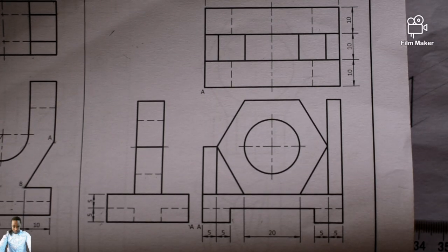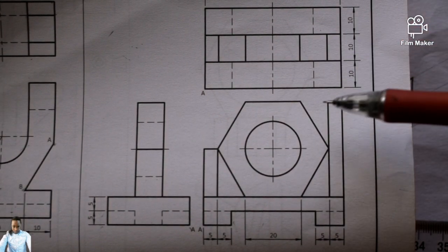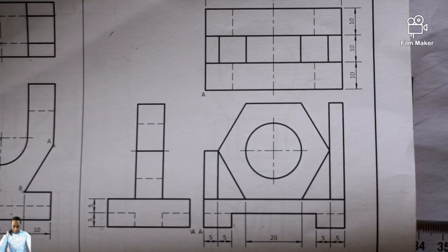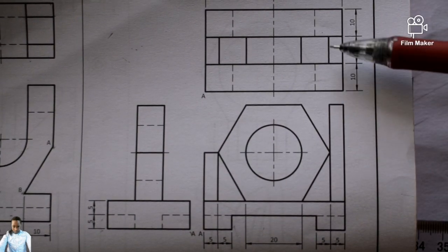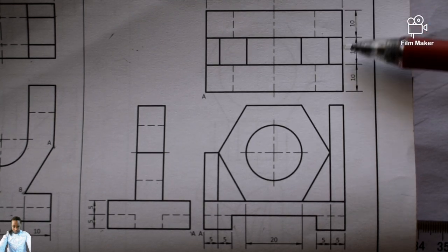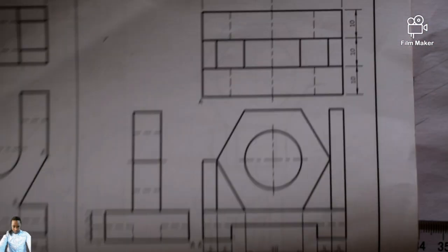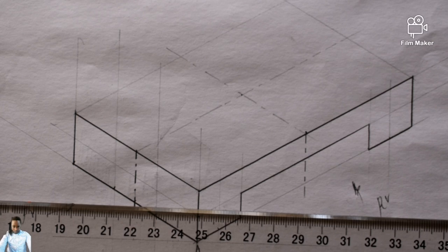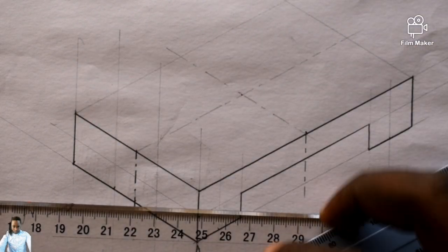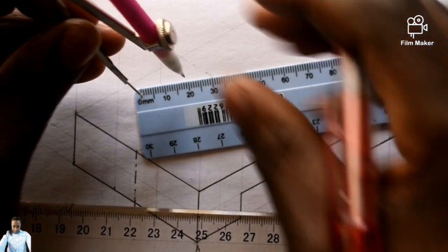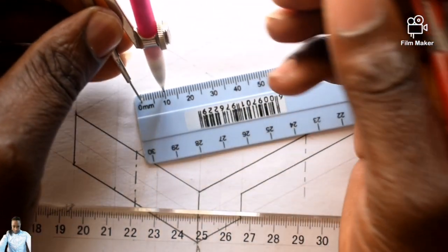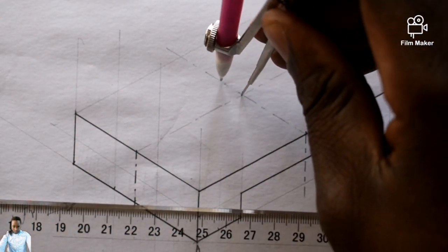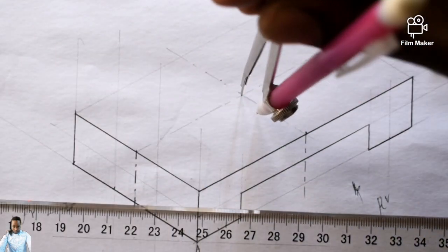And the thickness of it is how much? Is 10 millimeter. The thickness of this hexagon of ours is 10 millimeter, which is from here till here. We are being told a dimension for us there, up there by your top view. So it's 10 millimeter. So I am going to say 10 millimeter times 2 is giving me 20, right? Then divide by 2 is giving me 10 back. So I can simply open my drawing compass to 10 millimeter. This is 10, right? So I come and place it at this point. I mark here and I mark here.